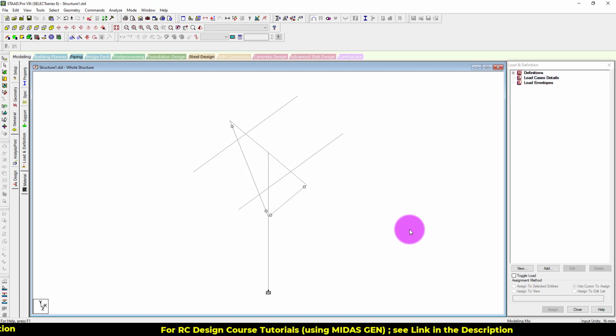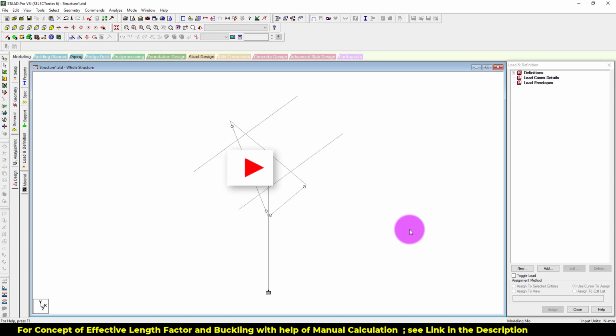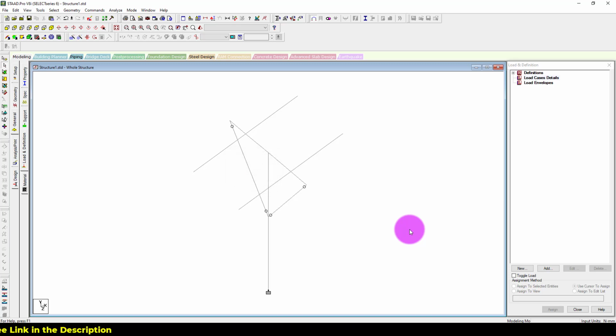In that sheet, there will be load calculation for dead load of the solar panel, load calculation for the wind load of the solar panel, and not only the calculated ones. That sheet is able to transfer those calculated loads to the corresponding software by using some algorithm. And I have developed that sheet by using VBA macros, which is actually a programming language.